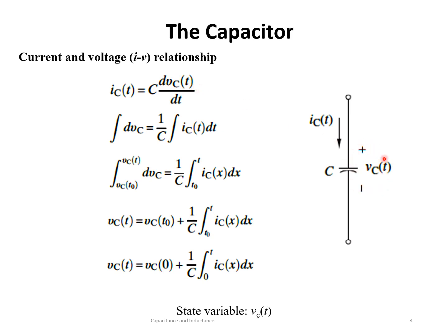The voltage across the capacitor with this polarity and with this direction of the current. This is very important. All these relations use this passive sign convention. With this voltage polarity and with this direction of the current, the mathematical expression of the current iC is C dVc by dt.